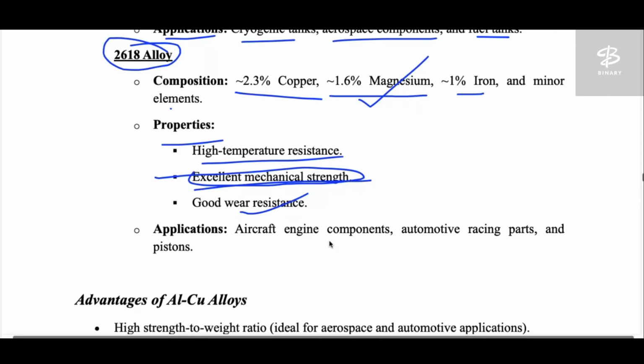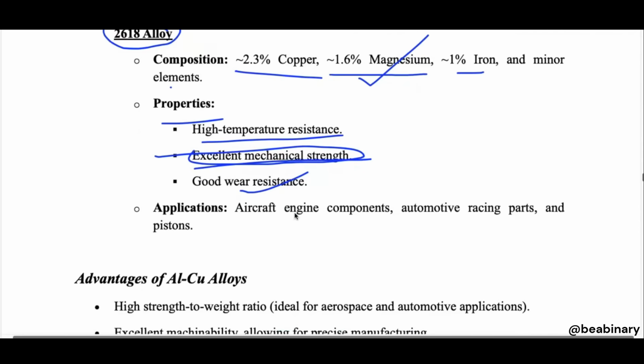But the difference is the other element that comes into the picture: relative motion. In wear, they are in contact and have relative motion. But in case of corrosion, there is no such relative motion; there is a chemical reaction due to the nearby environment. So this is the difference. In both cases, the material will reduce its efficiency, and its strength and properties will be reduced.